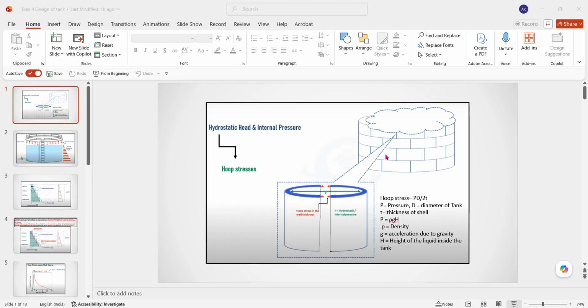Here, above 61 meter, when your material requirement is the prime criteria, at that time you have to use the variable method. Here the thickness calculation will be less than the 1 foot method, and it is a repetitive method. You have to calculate the stresses at different levels of the shell, each course, and the stresses are very close to your hoop stresses, and it permits larger diameter tank for the same maximum thickness.